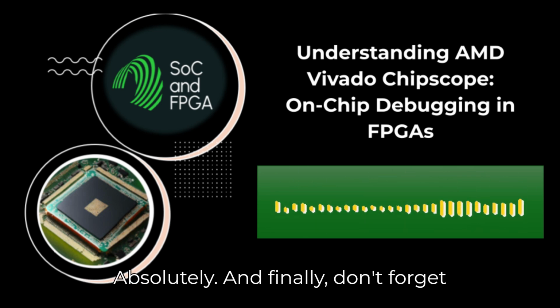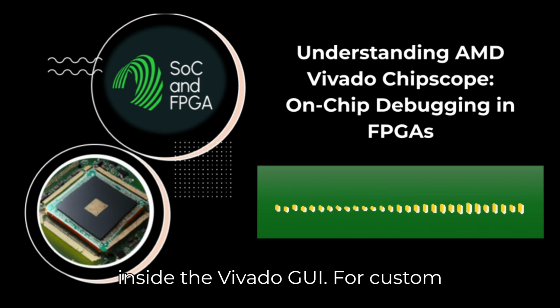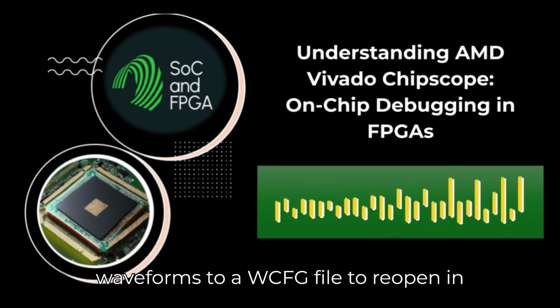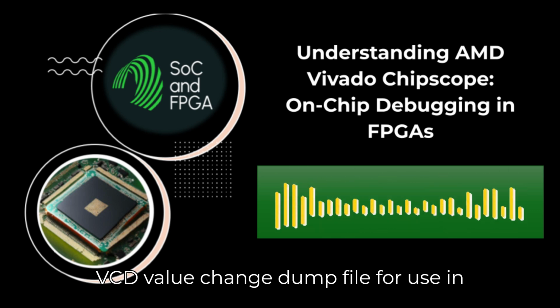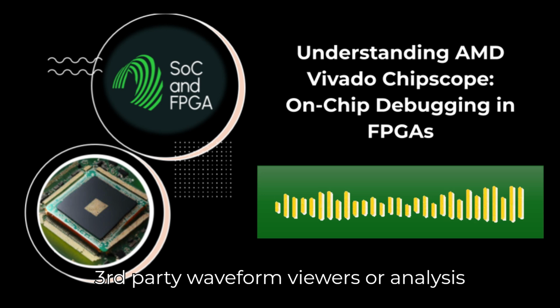Absolutely. And finally, don't forget that the captured data isn't trapped inside the Vivado GUI. For custom analysis, you can export it. You can save waveforms to a .wcfg file to reopen in Vivado later, or export to a standard .vcd value change dump file for use in third-party waveform viewers or analysis tools.